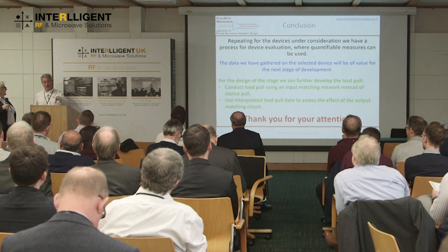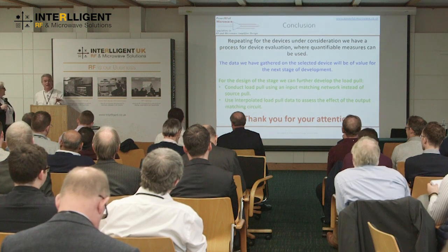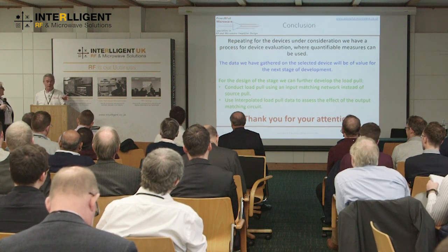Actually, although all that analysis was on the 25 watt, we went for two 10 watts in parallel because of that input matching and the ease of reflecting the power into the quad hybrids. But we were lucky that for 500 megs to 3 gigs, there are quad hybrids available. You don't always have that.